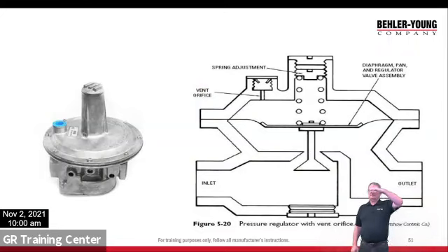Number one is that diaphragm moves up and down. It needs to be able to move air too. So it'll push air out the vent, pull air back in, push air out. But if that little diaphragm ruptures, it's going to leak out there. All right. So that's the regulator.